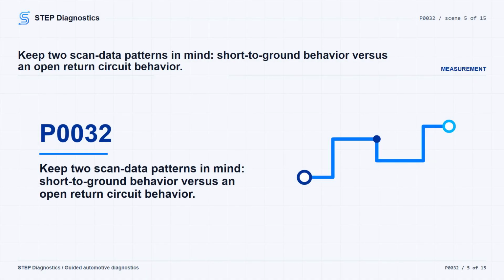There are a couple of signal patterns worth keeping in mind while you diagnose the heater circuit. If the O2 sensor signal is shorted to ground cold, the bias signal voltage can be at 0 volts, while the 0-1 raw voltage signal will read -2.5 volts and increase towards 0 volts as the sensor heats up. Once warm, both can read near 0 volts.